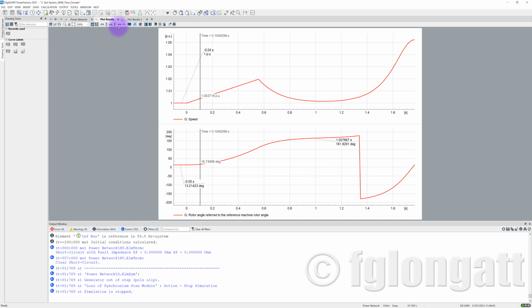Here, because we are using time domain simulations, we calculate the critical clearing time. To be honest, if some of you go to the industry, to the transmission system operator, to any utility, the critical clearing angle is not useful. It's not useful because the angle is not a useful information for the basic protection system. From the protection point of view, time is the most important variable. Time is the most important variable because it defines the exposure of the equipment to the short circuit faults and so on. That is the reason that the critical clearing time is the important variable.